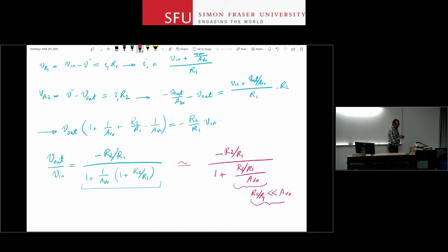In a case like that, what you can do is divide the task between 2 amplifier stages. Have a gain of, let's say, 1,000 for the first amplifier stage, go from a microvolt to a millivolt, and then have another stage with a gain of 1,000 and go from a millivolt to a volt if you need to. In both cases, 1,000 is significantly less than 1,000,000. You should be okay. And as I said, you have the same situation with the non-inverting configuration. The gain drops by the same factor, but the same argument applies.